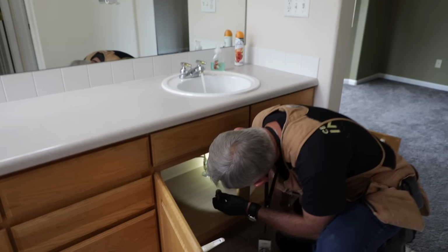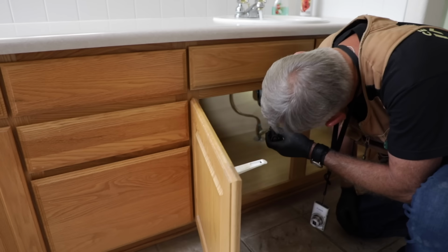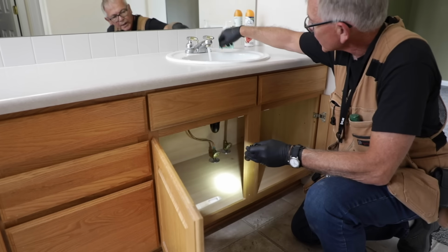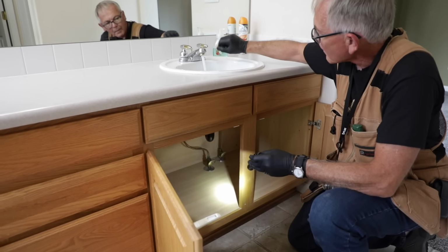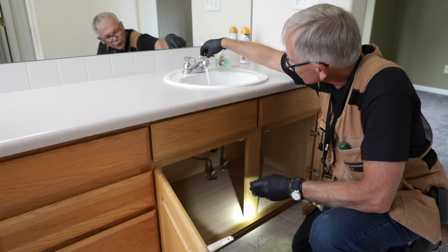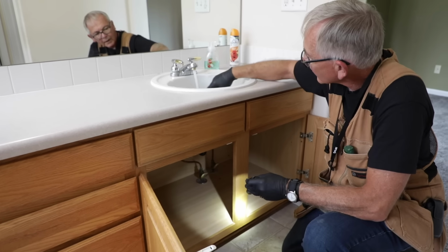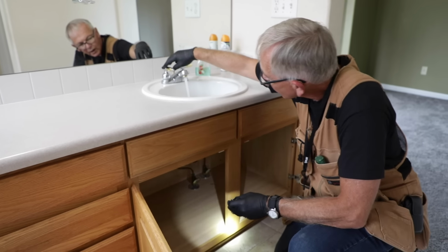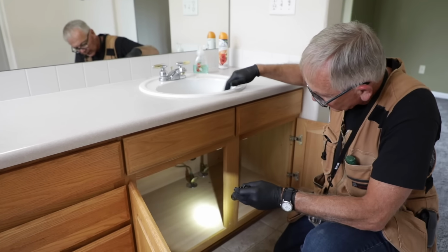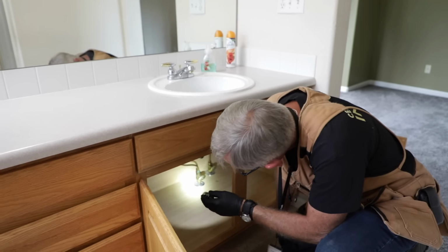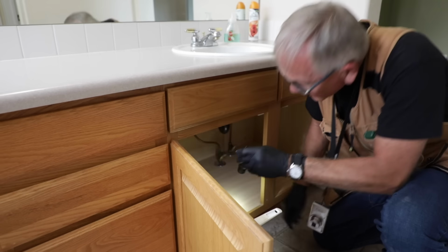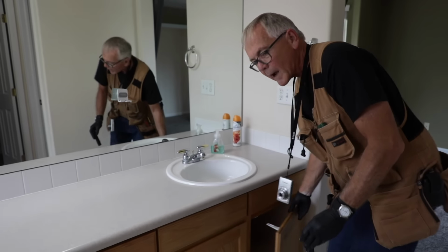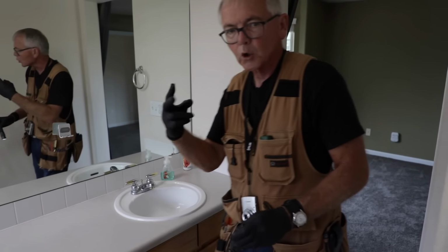So I'm going to go down below, start looking for any leaks that might be happening. I'm not seeing anything on this sink. So now I'm going to verify my hot water. I'll shut my cold off. Make sure the other side's hot and I got hot water. So I verified that. Take one more look. Everything looks good on that sink. This particular bathroom is the master bath and it has dual sinks.